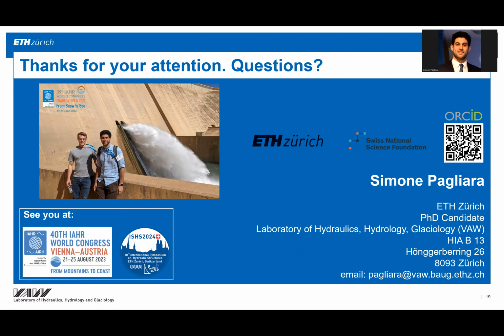The only thing that we can do to limit that is to increase our Reynolds numbers so that we are in a very turbulent regime, trying to match the Reynolds number of the prototype in order to have the viscous effect be as small as possible. But except for changing the viscosity of the fluid, which is not something we can do at the moment with such fast flows, I see it as an intrinsic limitation of physical modeling, and I don't see any way to completely overcome that.